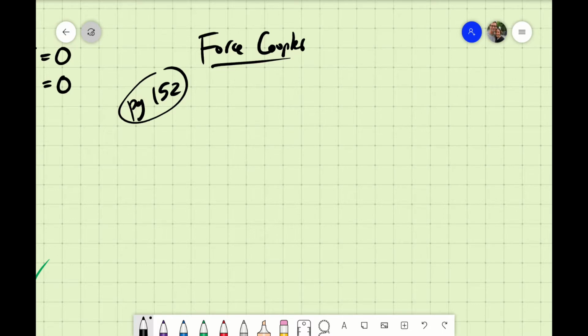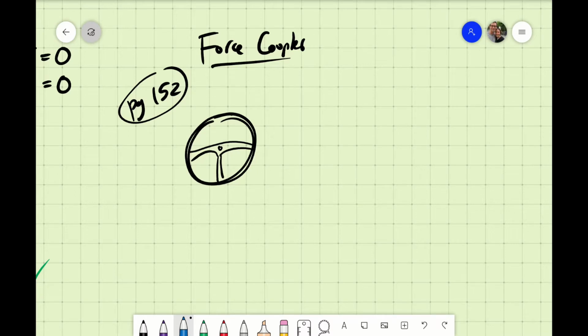This is just the idea that we often, even instinctively, produce two moments at the same time when we are turning something. It happens all the time. We turn stuff with our hands. He gives the example of a steering wheel. And we naturally push one direction and pull down in the other. And I'm using the same letter because they are the same thing. He actually used negative F. I didn't like that because he already drew the arrow going the other way. So personally, I'd rather that he let the direction do the talking instead of trying to doubly say it with a negative as well.